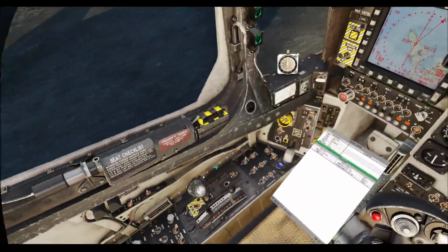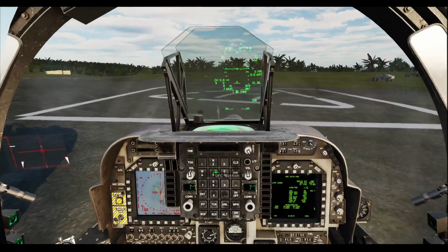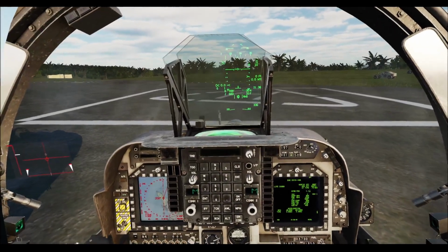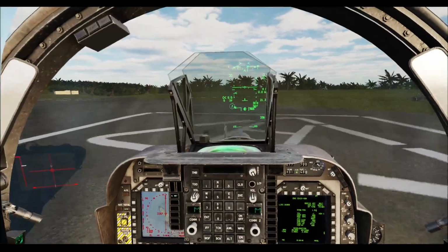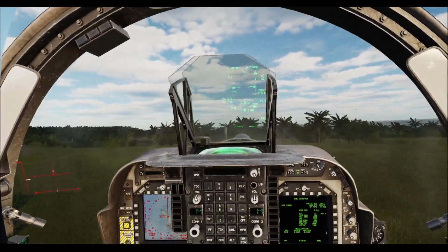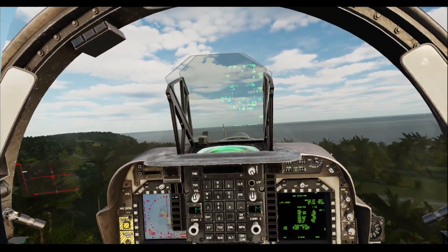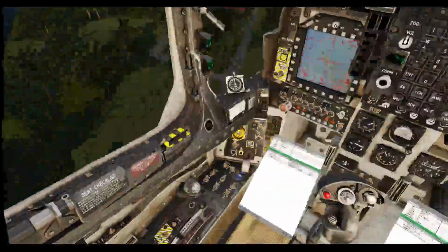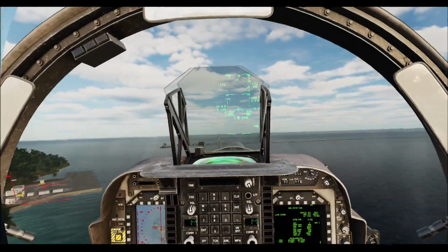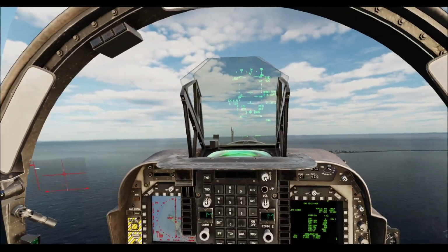Okay, so let's take the parking brake off, clear the master caution, hold the brakes, let's add the power. There's the skid and release, let the aircraft roll forward, bring the nozzles back to 70, bring the nose up, and capture attitude technique. There's 25, power, stow stop, water. Allow the aircraft to continue to climb. Check we're on the center line.